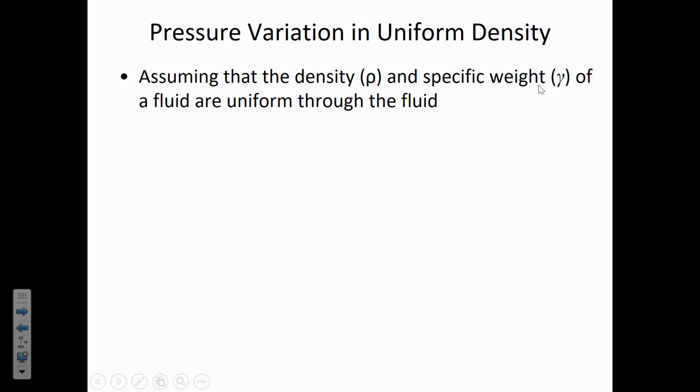As you get higher up, the pressure goes down, and so does the density of the gas because it's expanded. But if we're only going up or down a relatively small number of meters, then it's still okay for us to assume this constant density even for gases. But for liquids it's fine, because as long as the constant temperature applies, liquids have the same density as you go down through the fluid.